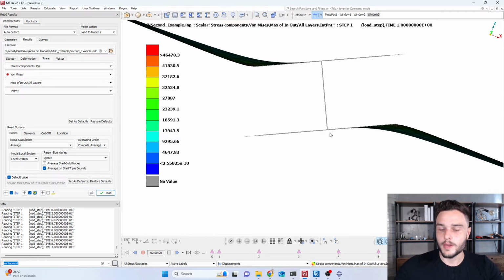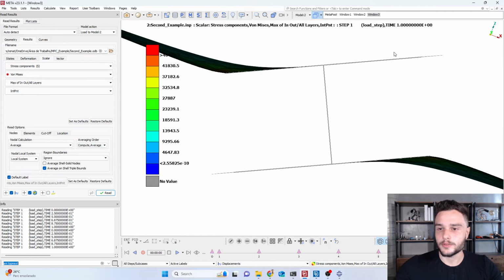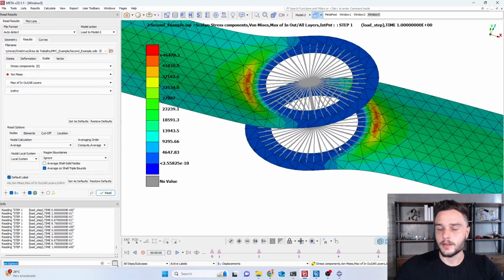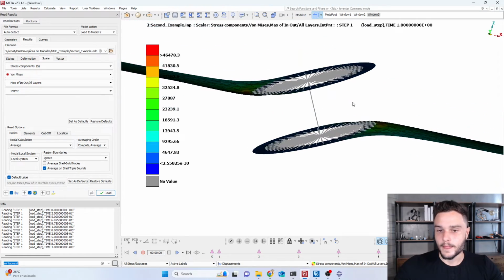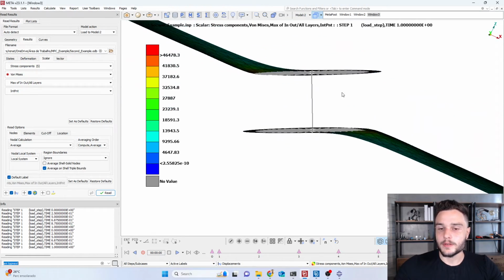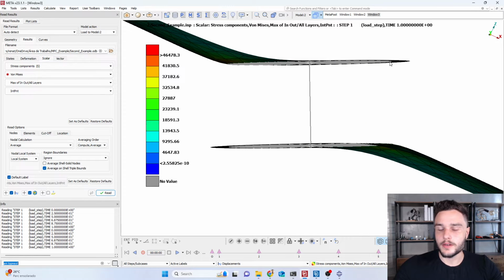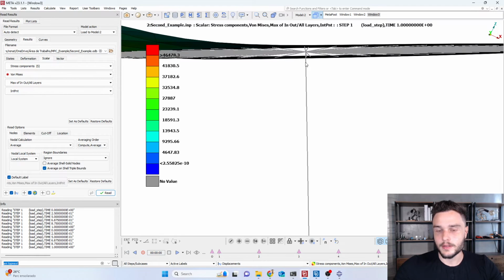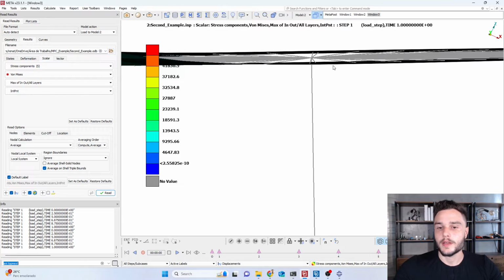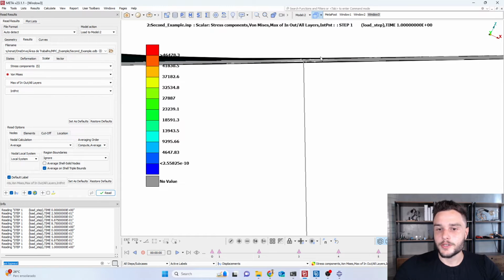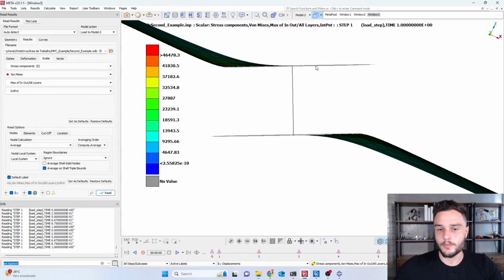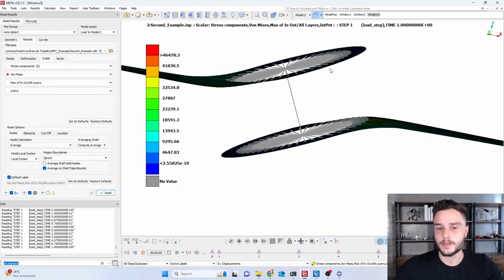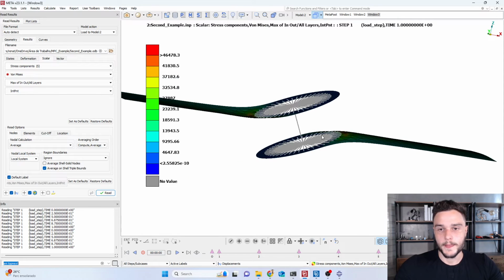The direction of the MPC is yet normal to the surface where we have the coupling. This is because everything here is rigid and nothing can change. The angle cannot change because if it changed, that means that it had deformed, and then we would have a stiffness associated to that.